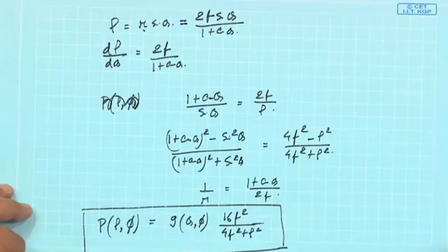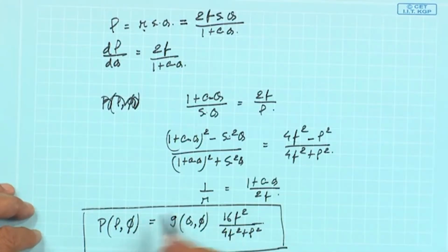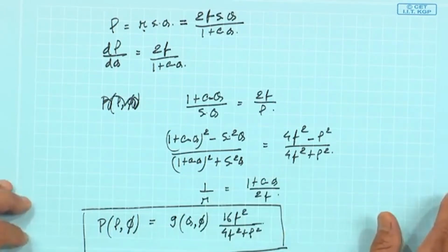Now from here we will take certain things. Please note, actually due to lack of time we did not do that. If an aperture is illuminated uniformly, that gives us the maximum radiation. That means the radiation is in the broadside direction and peaks. Actually from array theory concept you can see that when we uniformly illuminate the array elements, then you get a peak. In other cases you do not get, because all are not constructively added.